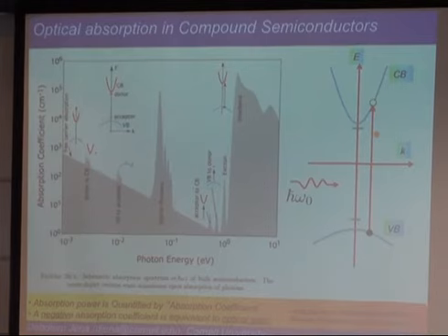One of the reasons for that is the symmetry of the bands, of the energy states at the top of the valence band and the bottom of the conduction band. They are right, so that they are direct band gap. And the symmetries are right. We'll see that the symmetry of this state is S-like, S orbital-like, is isotropic. And this we'll see is P orbital-like. So it means it is elongated in a certain direction.